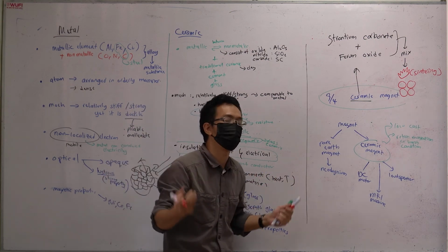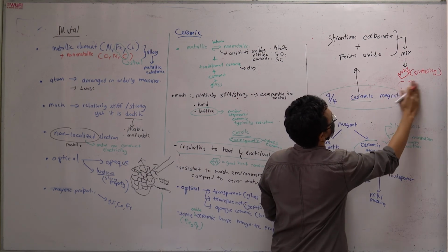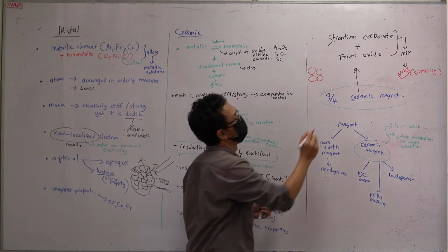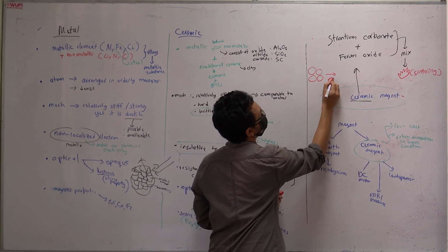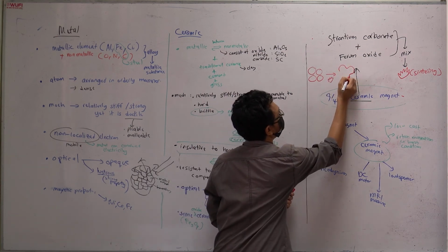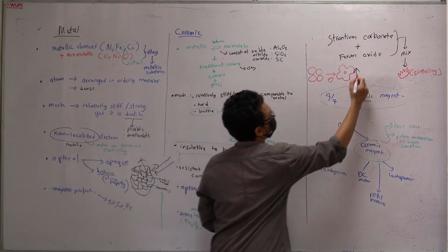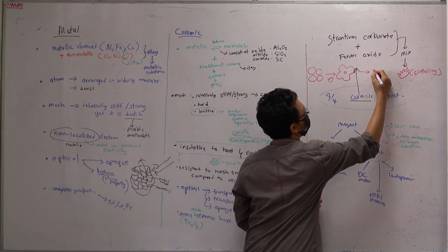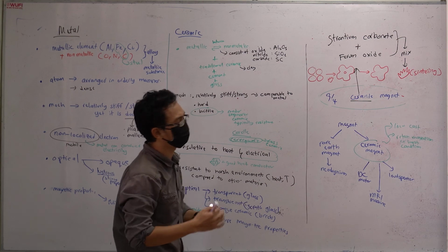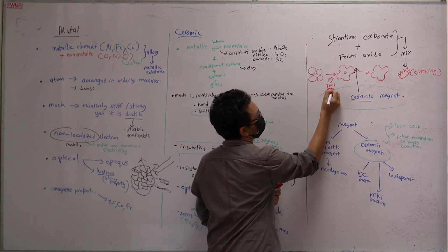You need to put a lot of pressure and also temperature. You can't see it well here, so I put it here. Let's say you have these four powder particles. When you heat it and put it under pressure, what happens? You get something fused like this. Then further on, you get a mass like that, with holes. So basically you fuse the thing using temperature and also pressure.